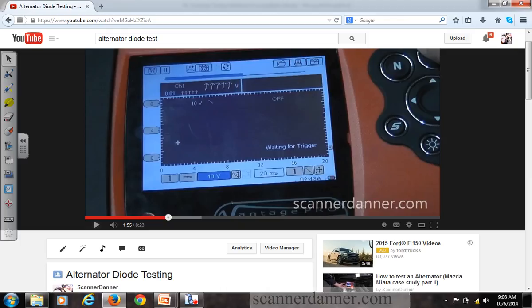By the way, there's no such thing, guys, on a voltage setting of out of limit. You're not on the right scale, period. There's no such thing as what we're seeing here, which is out of limit. It is out of limit, but it's out of limit for the scale you picked. So I don't ever want to hear I have an OL on voltage. You say OL on voltage, you're on the wrong scale. Not the same thing with an ohm meter.